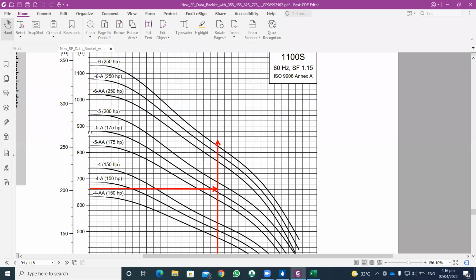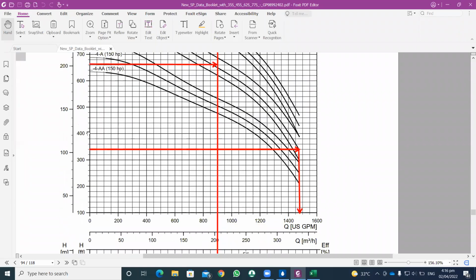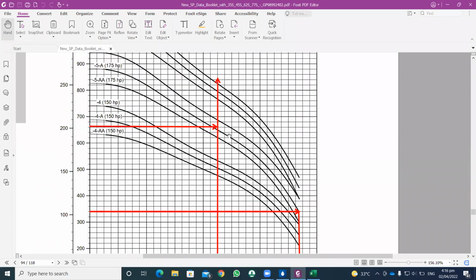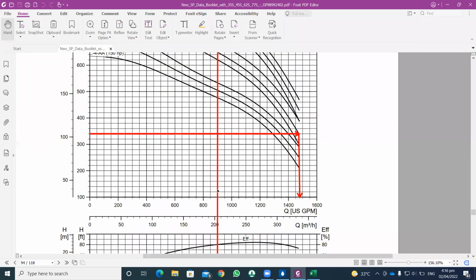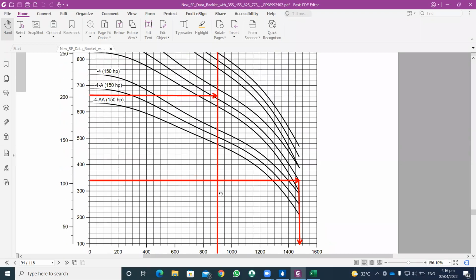For this pump, the 880 feet is the shut off head, having zero supply of water to the system, and then I use a design value of about 660 feet, giving a discharge of water to the system of about 840 gallons per minute.